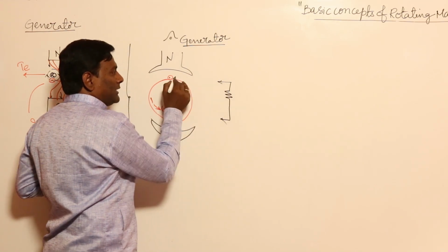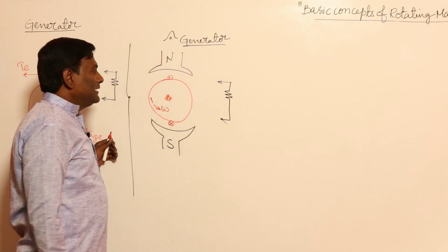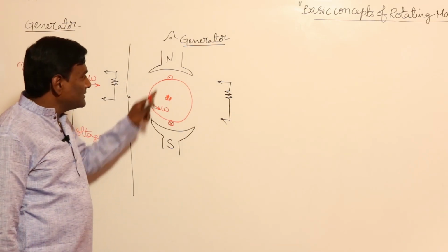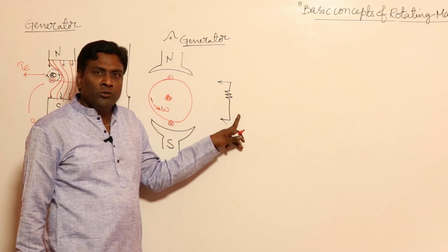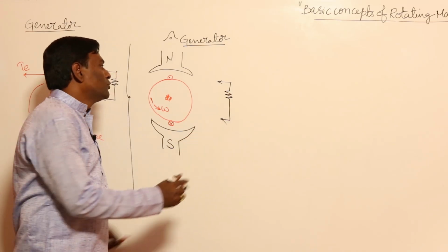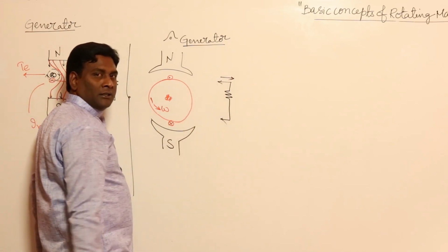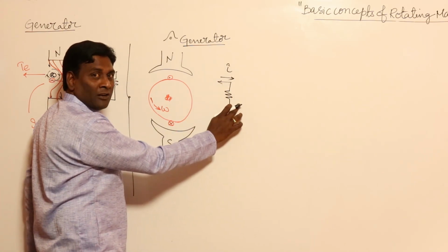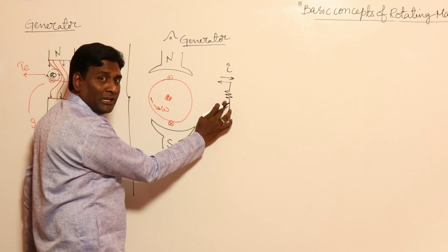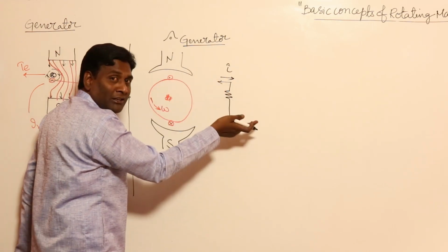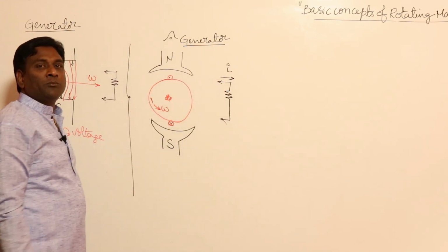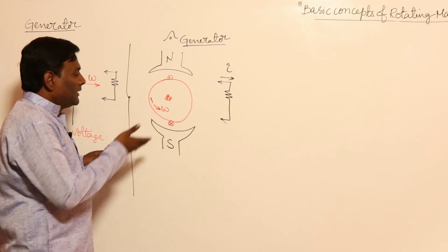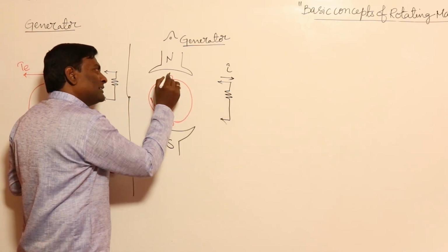across these two. Then what will happen? Currents will flow, because voltages are there and you are connecting a load, so you are showing a path to electrical current. So some currents will flow here. Some currents are flowing here, which means you are absorbing electrical form of power. The generator has to deliver electrical form of power, so the generator has to absorb mechanical form of power.